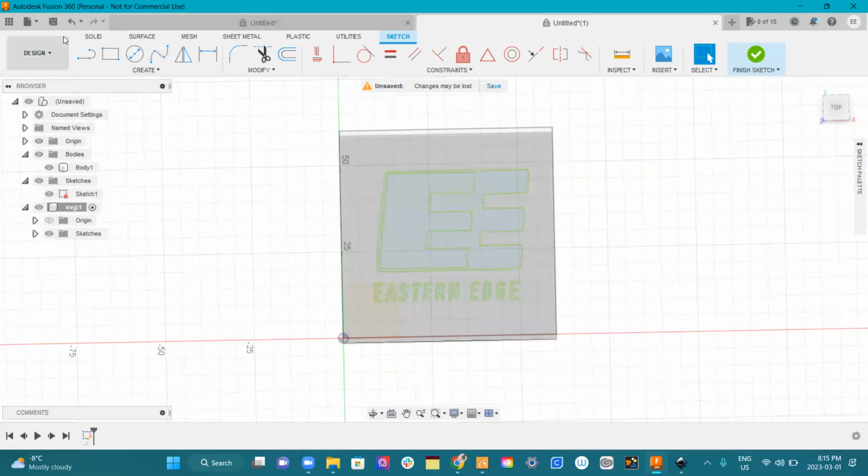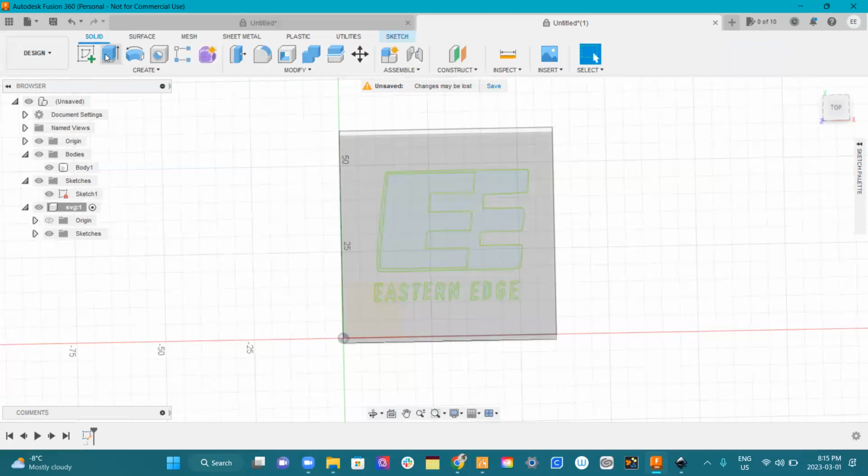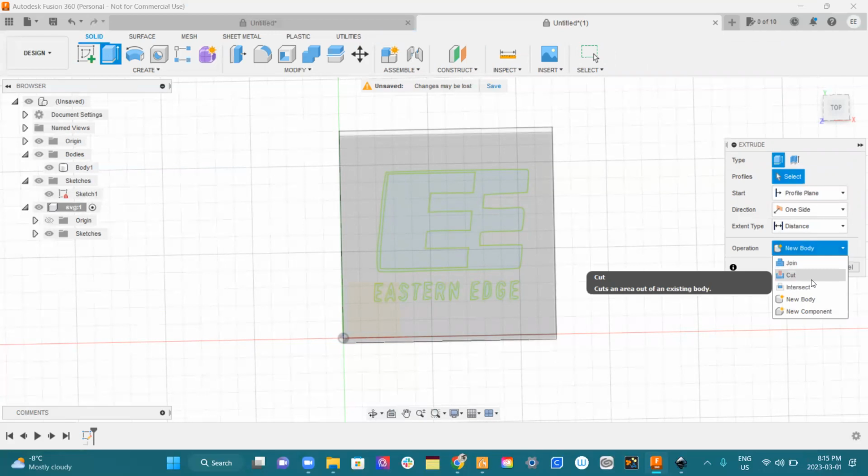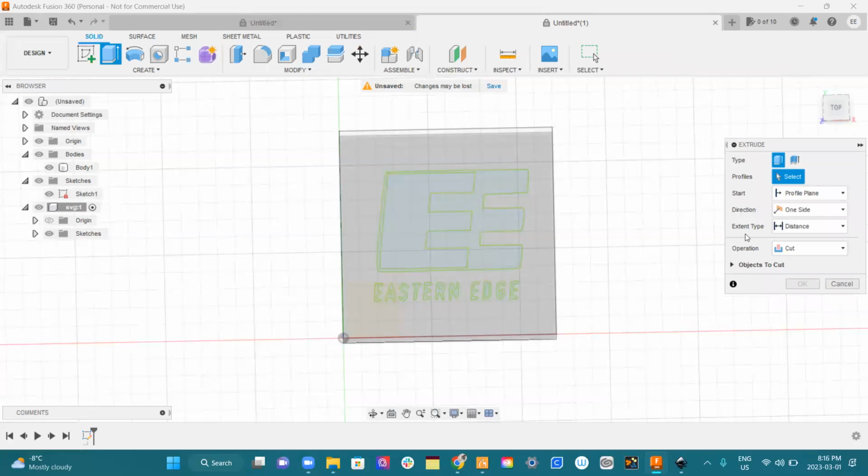And so this is still a drawing. I go to solid, I go to extrude, and I'm not extruding out a thing. I'm not putting a bump on my piece of wood. I'm going to cut in, so you have to select the operation. There's all these little fiddly things. This piece of software is enormous. People spend a lot of time learning it. There are a lot of guides online though. So if you want to just waste an afternoon figuring out fillets or chamfers, it's there.